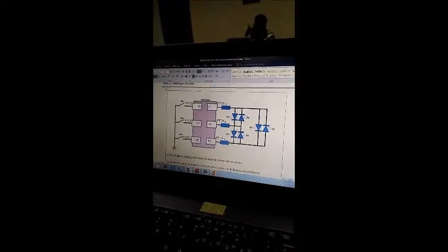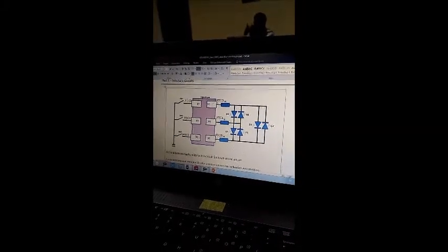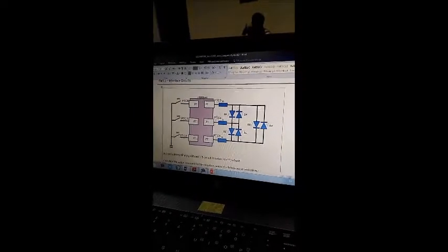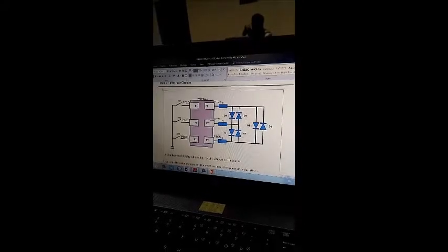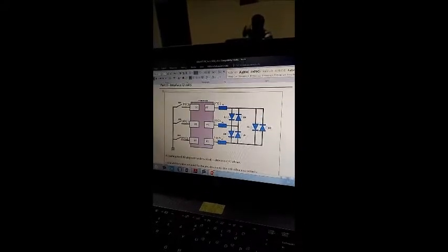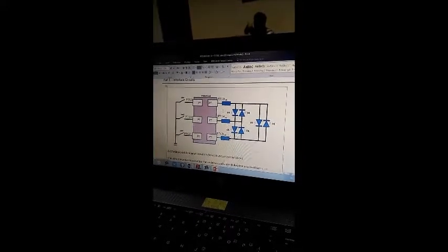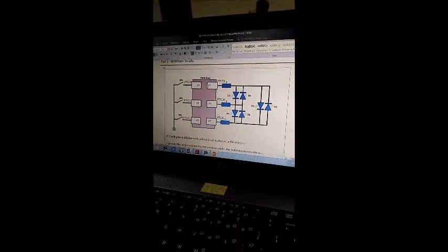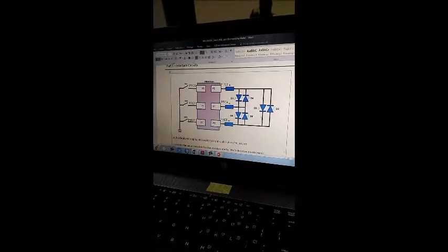This is the CharliePlexing circuit. Providing 3 inputs to the Freedom board, it will give 3 outputs. By setting the output to be the data direction PDDR 1 for out and PDDR 0 for in, we can control the lighting up of LEDs individually.